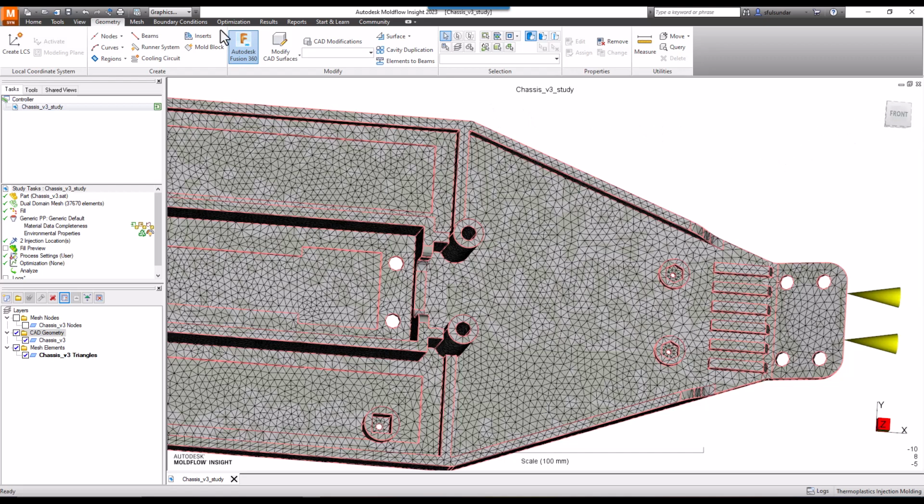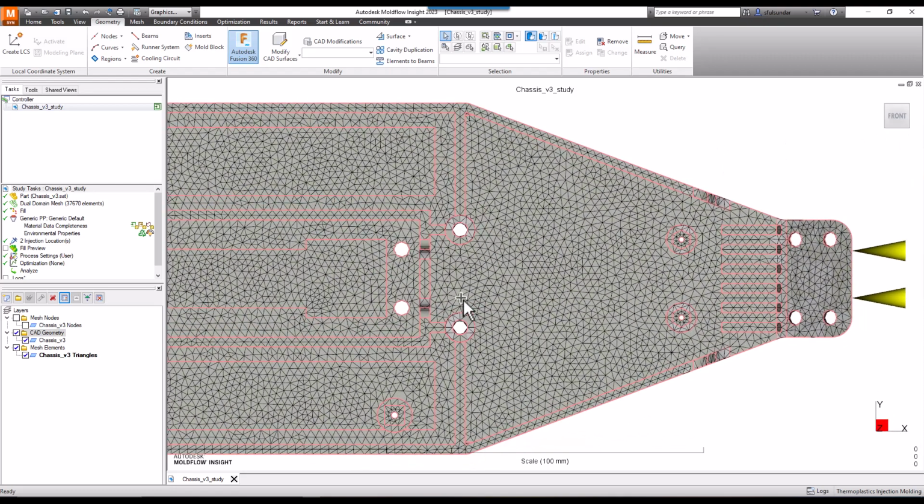Well, if you have Fusion 360 installed on your machine and Moldflow on the same machine, you can quickly edit the geometry and come back and do the flow leader or flow deflector or whatsoever you want to do for the element selections. Of course, flow leaders and deflectors can be created in Fusion 360 as well. But let's give a try how we can split the faces, particularly, which will help us to select the set of elements.